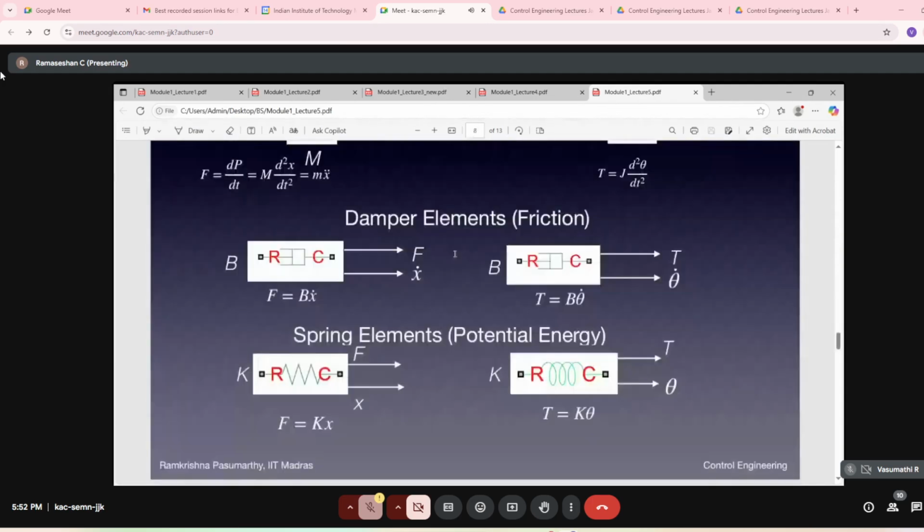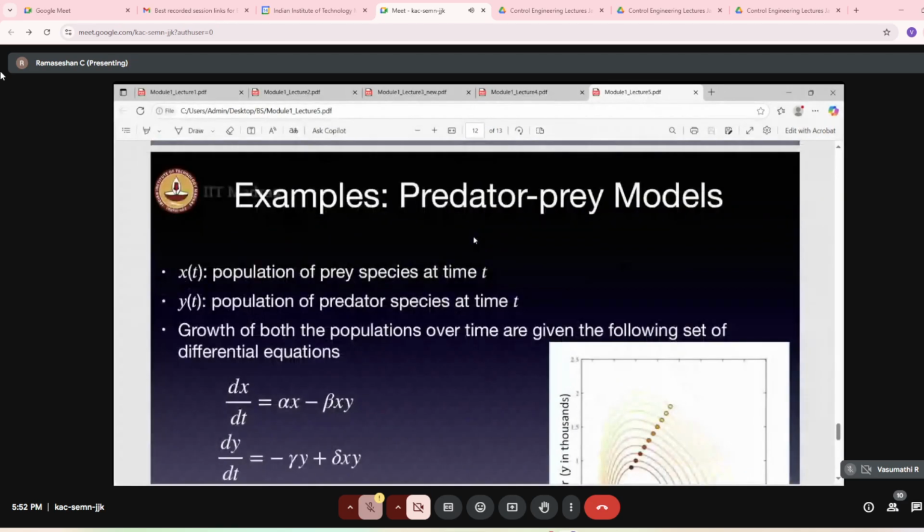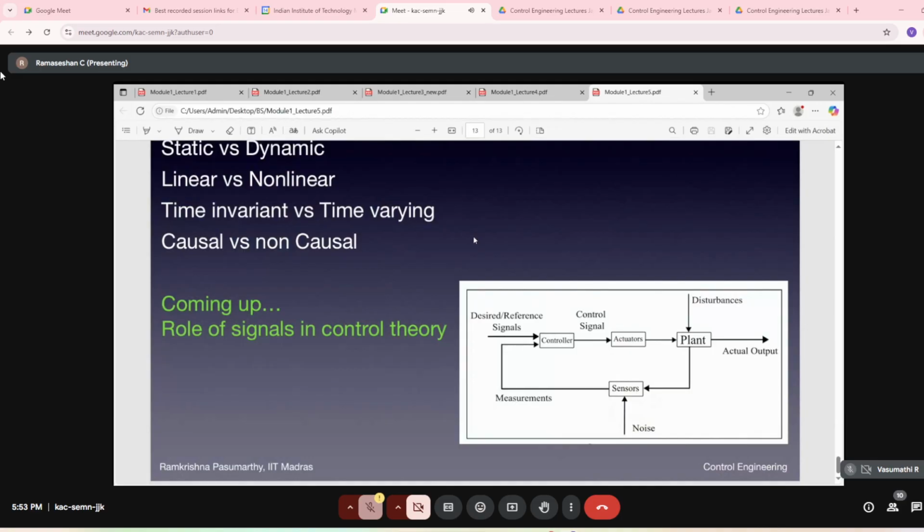Systems technically they are not. Most systems in the real world are actually causal. The state now depends on the state at a previous time, but they don't depend on the state at the future. That is nonsense for most systems. But it's a mathematical ideal that will be kind of useful when you go for controller design.